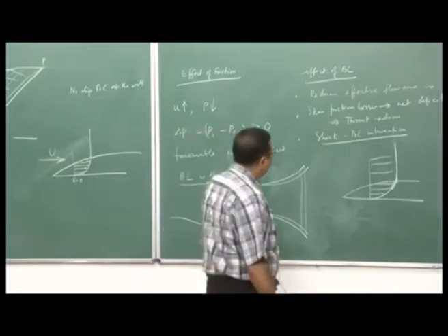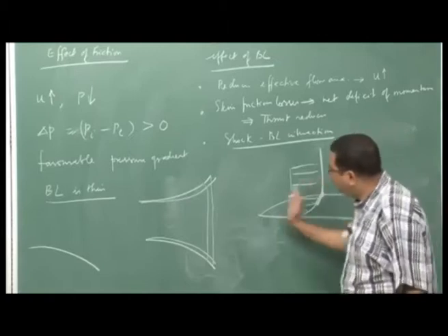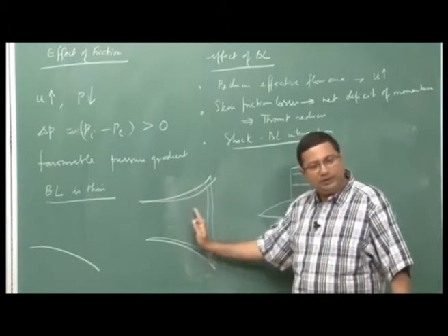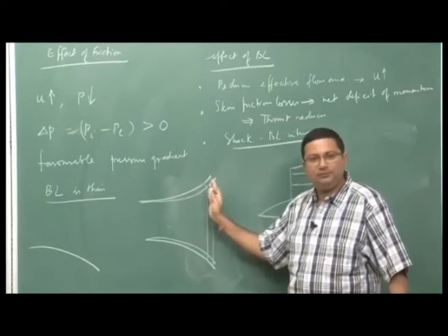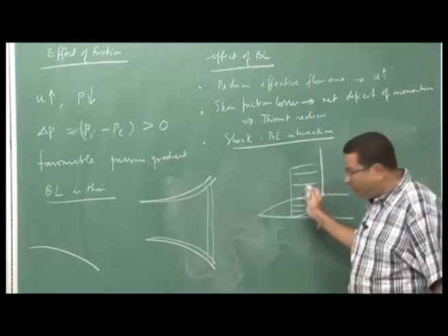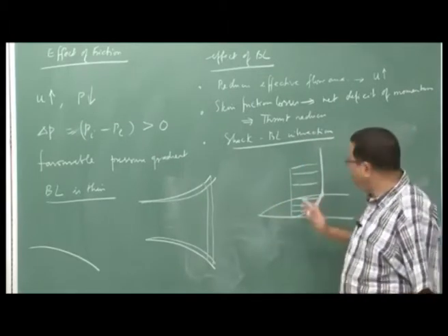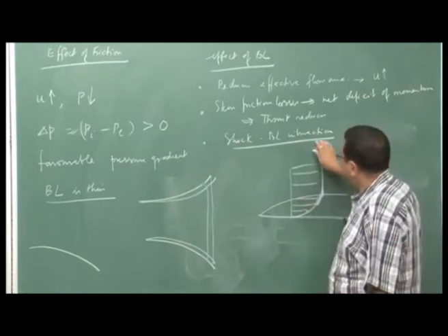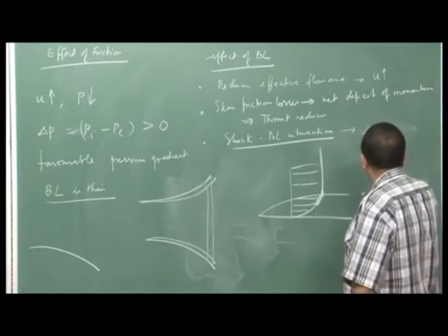Okay. So, there are two things. First of all, at certain ambient conditions, there can be a shock wave entering. That is a different phenomenon where it is going to interact with the boundary layer and create some nasty problems. In other cases also, because the flow has to become subsonic in this zone, there can be a shock wave, and because of that the shock boundary layer interaction can occur, which may lead to separation.